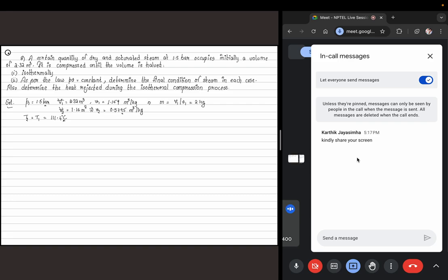If you look at the PV plot, so you have P and V. Initially you're on the saturated region at a certain pressure of 1.5 bar. Now you are going isothermal, all you are doing is compressing it. So your specific volume is getting reduced, and you are moving in this direction. If you happen to be within the dome, you're still at the same pressure.